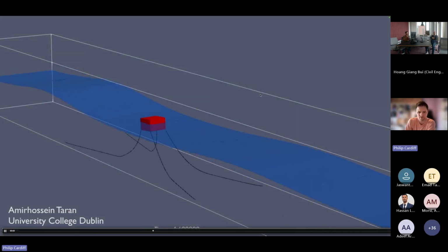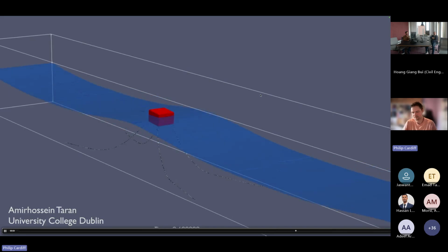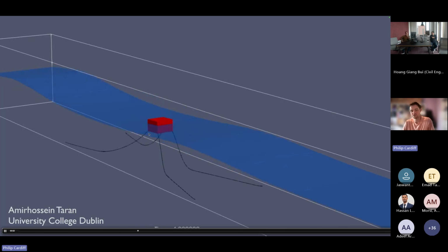Just one other one to do with some of the research I'm involved in as well. So let's say continuum style formulations for solid mechanics is definitely one thing of interest, but there's also, let's say, structural formulations. So in this case, these are beams. These beams are actually fully implemented in OpenFOAM, and they're a finite volume formulation for beams. So these are Simo-Reissner beams implemented in OpenFOAM, and they're used as mooring constraints in the interFoam solver in OpenFOAM. So this is basically an interFoam fluid simulation, and then you have these mooring beams.